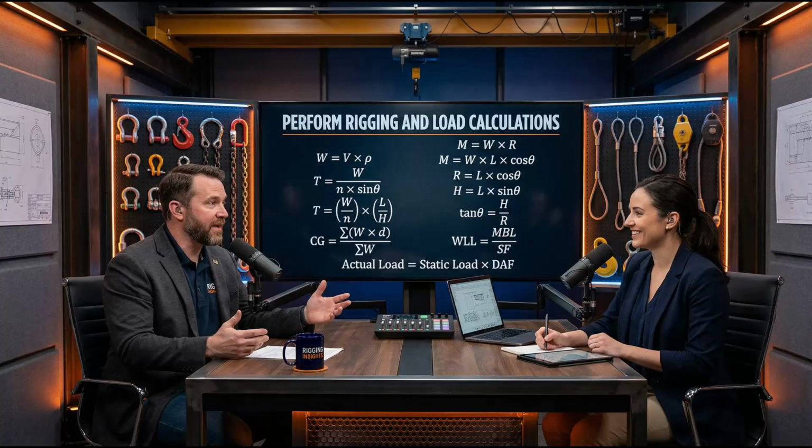15 degrees isn't that much. But that stretched jaw is physical proof that the molecular structure of the steel has been compromised. It will no longer hold its rated capacity, and it will eventually fail without warning.